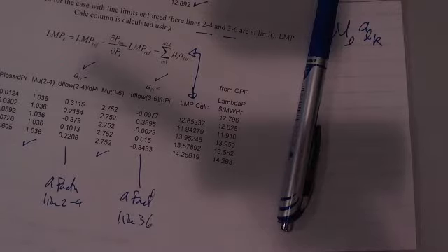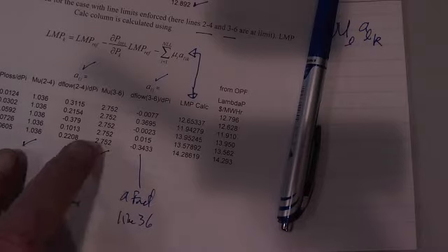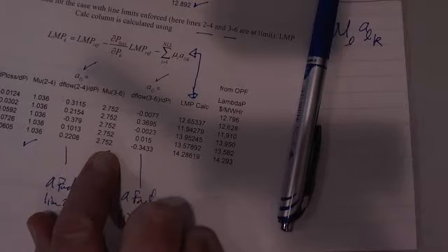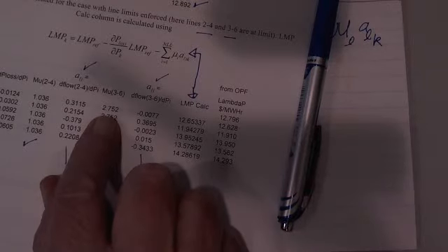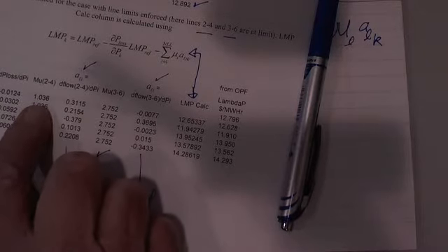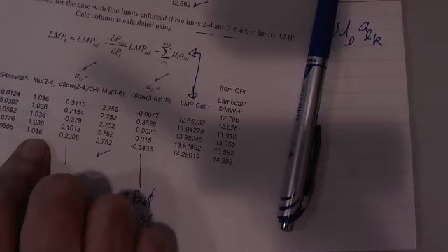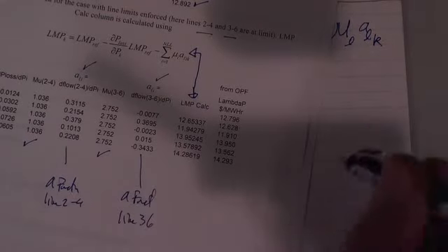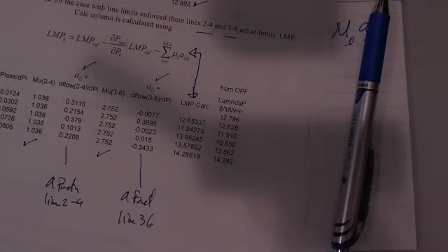And so if I relax the constraint, the mu factors, you notice here, and here, and here, this constraint here, if I were to relax that constraint by 1 megawatt, my cost would change by about 275. This one, it would only change by 1.038. So it's a very different mu. But the mu gives you a reading on how much each constraint is affecting the total cost of the problem. And that's just a little bit of an aside.